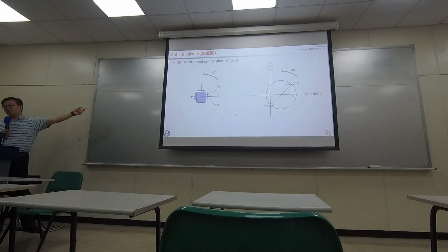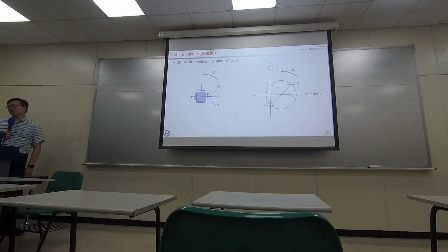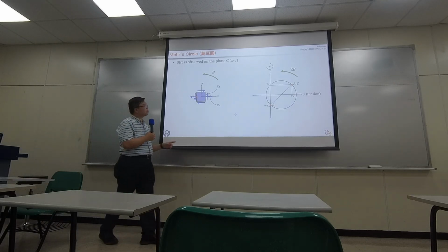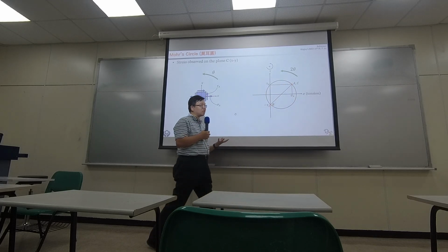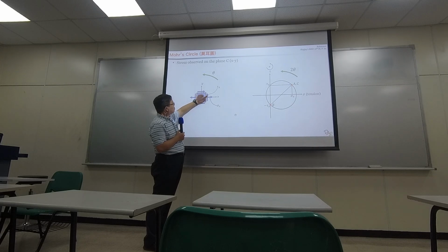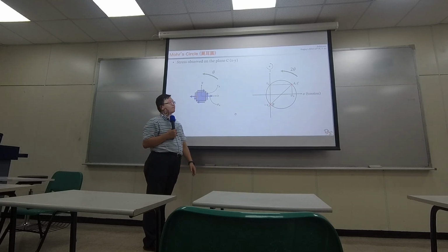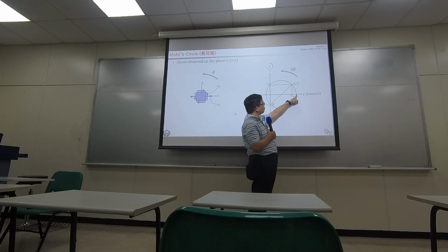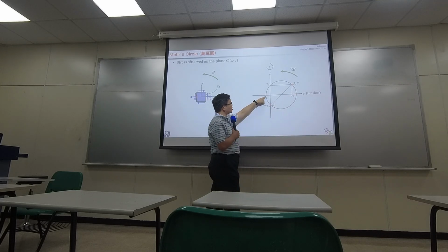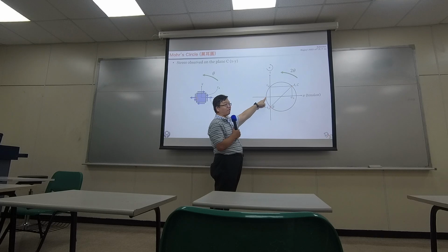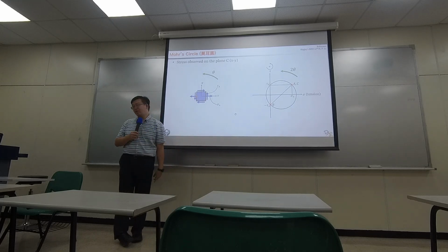Okay, so you can make a circle like this. Whenever you turn theta degrees on the left in the real world, in the Mohr circle coordinate, you will be making a turn of 2 theta degrees. And for every position on the circle, basically that would be the load condition for the element in different angles. Then you realize there is a point right here where you will have the largest normal stress. And there's another point right here, this position, you have the smallest normal stress, the most negative normal stress. So that would be the position that we are looking for.